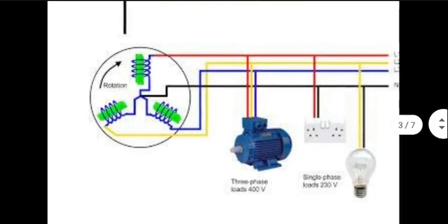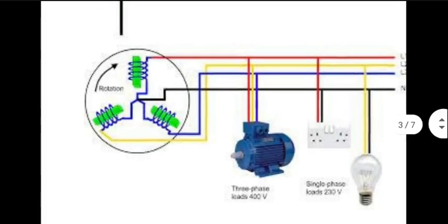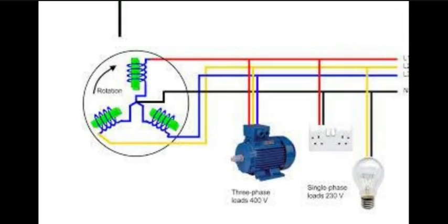What we do is we have three generators which are being shown through these symbols. A cylinder, on top of it conductors. That's how the rotor of the generator looks like. Okay. So three generators, one end of each connected together as a single node, and the other ends going out to the world, the other three ends. The things that the public sees are four wires coming out, one from the common point and three from the other three ends of the generators.